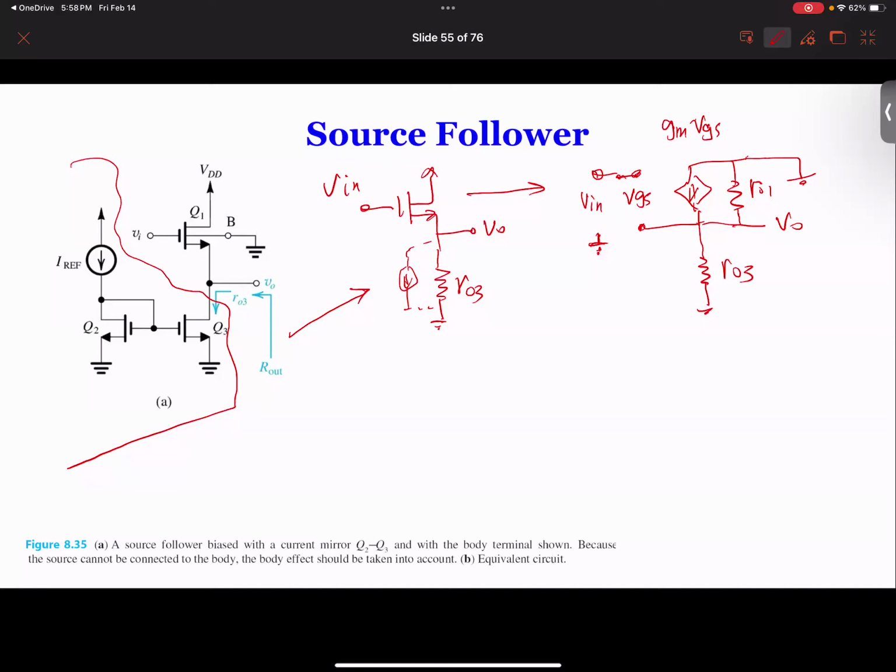I think one of the mistakes that students begin to make is mixing Vin and VGS. But in this case, Vin is not VGS. Why? Because Vin is relative to ground, but VGS is from gate to source. So therefore, VGS is not Vin. It's very important. Vin and VGS are different things.